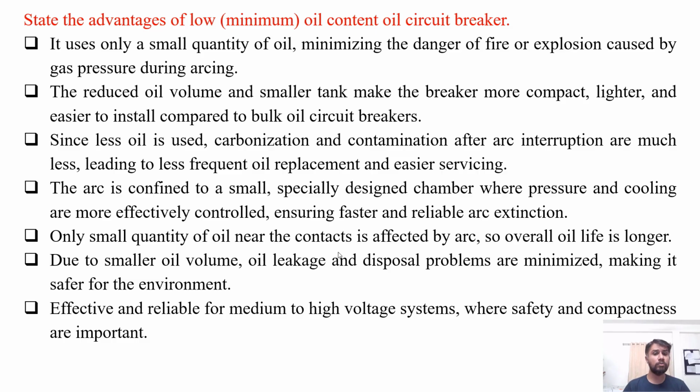The arc is confined to a small, specially designed chamber where pressure and cooling are more effectively controlled, ensuring faster and reliable arc extinction. Only a small quantity of oil near the contact is affected by the arc, so overall oil life is longer. Due to the smaller oil volume, oil leakage and disposal problems are minimized, making it safer for the environment. It is effective and reliable for medium to high voltage applications where safety and compactness are important. So these are several advantages of low oil content circuit breaker.